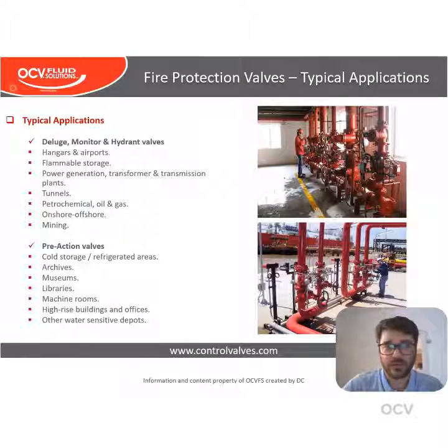Now we can see where these different valves are used. So if we're talking about deluge, monitor, and hydrant valves, we will see them at hangars and airports, flammable storage, power generation, tunnels, petrochemical, oil and gas industry, onshore and offshore installations, and mining. And if we're talking about pre-action valves, these will be used at cold storage or refrigerated areas and in other water-sensitive depots such as archives, museums, libraries, among others.